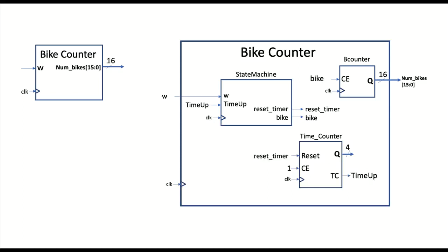But as long as you're using one of the outputs. One of the things Vivado does for you is it removes logic that you're not using. So for example, you have a nice 15-bit counter, and let's say you only want a 12-bit counter. Do you need to go and create a 12-bit counter? No. Use your 15-bit counter and just ignore the top 3 bits. Okay, Vivado will go and say, wait a minute, these flip-flops aren't going anywhere, and it'll go remove those flip-flops for you. And it'll go remove anything that's only going to those flip-flops, and remove anything else that's not needed.